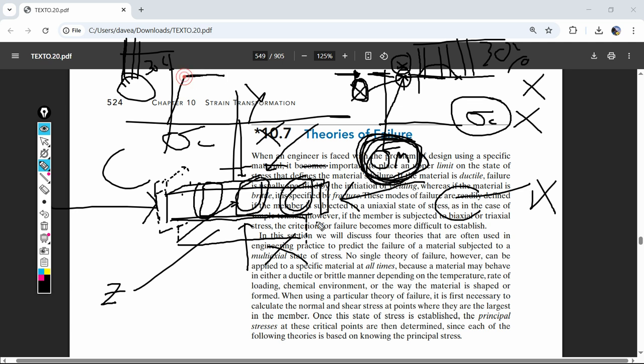They're going to talk about ductile materials yielding, and so you have to consider, is that the only thing holding this up? Because if it is, it's just going to lengthen and break. So right there is no different than right there if it's literally the only member. But if other things are taking the load after that one yields, then that one can still take this amount of tension. The tension doesn't go to zero, so that member is still holding that up.